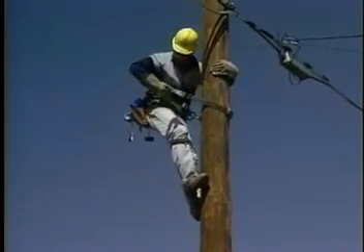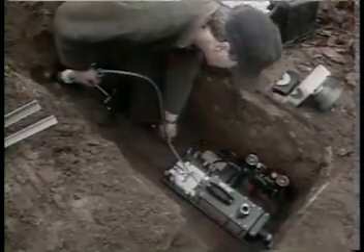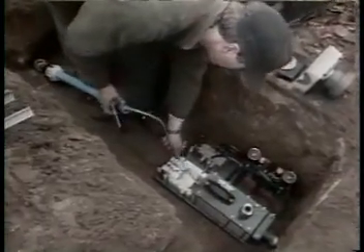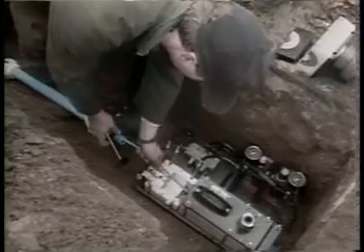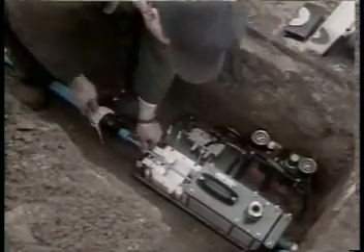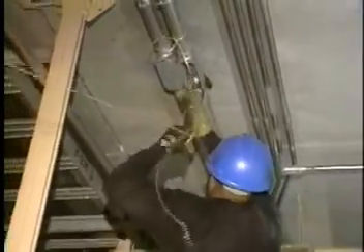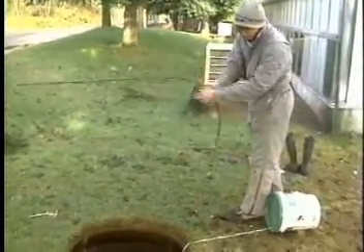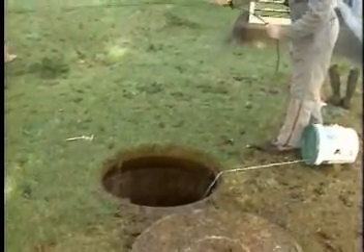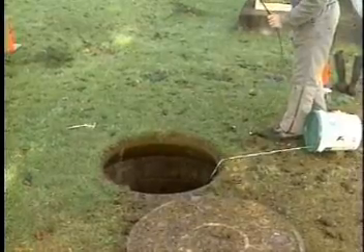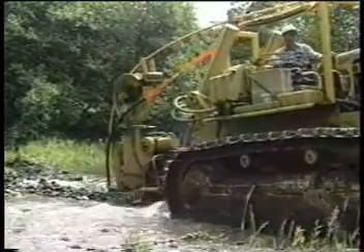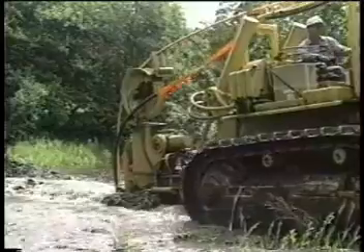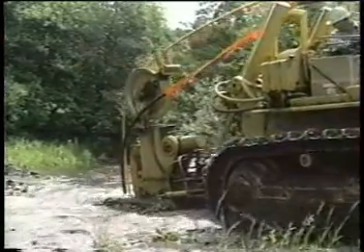Whatever equipment is used during installation, be sure to fully understand its operation and safety requirements. As stated earlier, a well-designed fiber system makes installation as easy and cost-effective as possible. Unexpected changes in the field are difficult, expensive, and may result in an unreliable fiber system. Only through careful installation can you ensure that the fiber cable will deliver top performance over the design life of the fiber system.